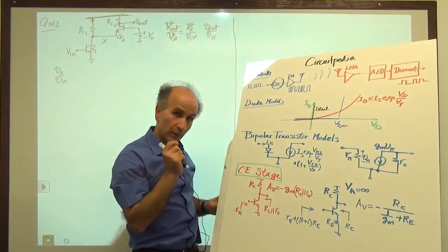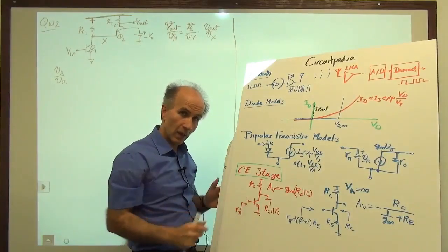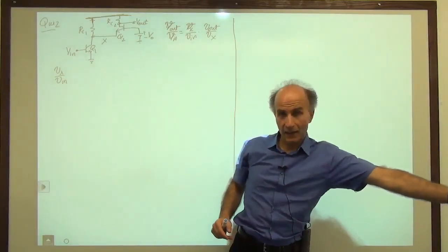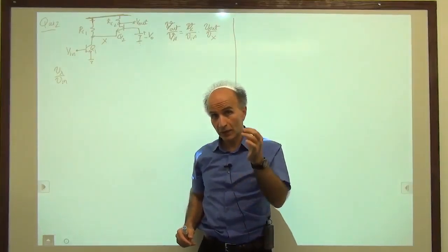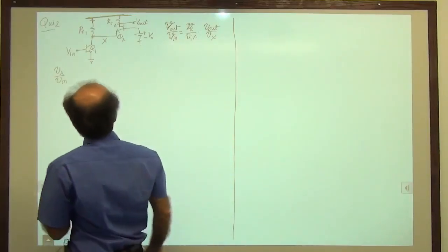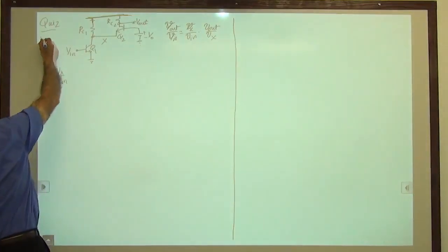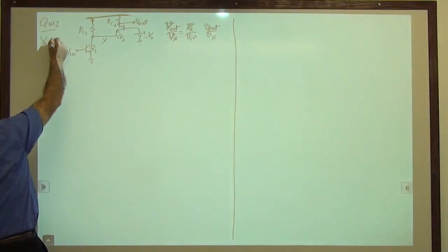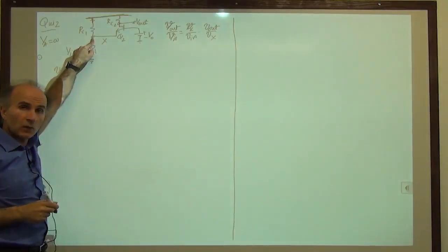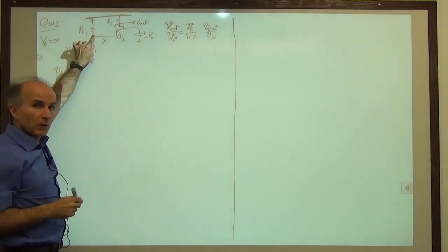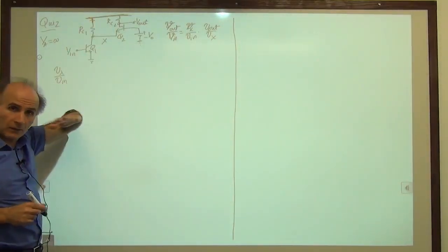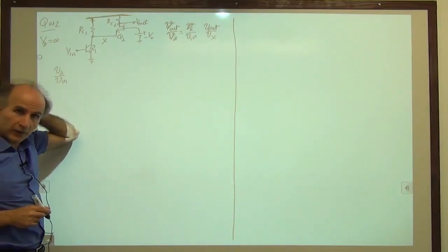But what we remember from verbalizing this equation was that we have to find the total resistance that is tied between the collector and AC ground. So here, we're assuming the early voltage is infinite for simplicity. If I sit here at the collector of Q1, I see RC1 to AC ground. VCC, this top rail, is always grounded because it doesn't change with time.